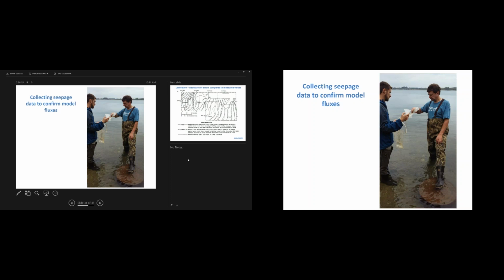USGS had a well on the causeway and the water level was 8 feet lower. So they were just using a sand permeability and that 8-foot head loss over 25 feet and saying a huge amount of water was leaving the lake. Well, if that were true, the lake would have been dry. We didn't really know what was going on in the lake bed, but we assumed that something was wrong and the lake wasn't leaking water like it should have.